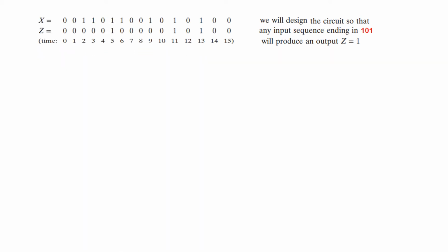So this is the given sequence, the inputs, all these values, and from here we write the output. And this is the timing circuit. Now, how to write the output, let me explain it. Remember, we are looking for 101, so the first bit is 1. When we go here, we find x is equal to 0, so it's not the desired bit, therefore the output will be 0. Move next, x is 0, so the output is still 0 because it is not the desired bit.